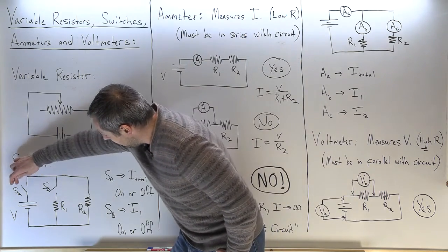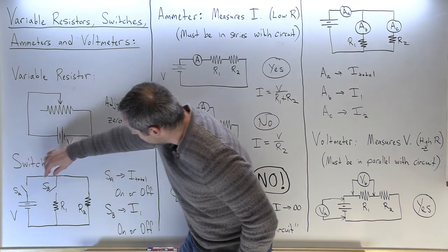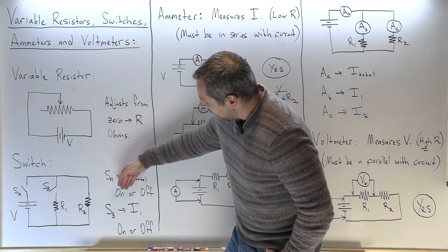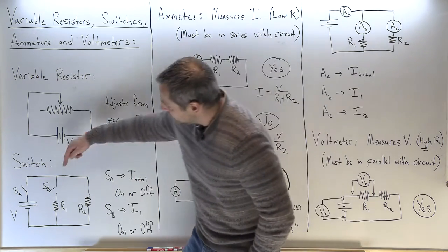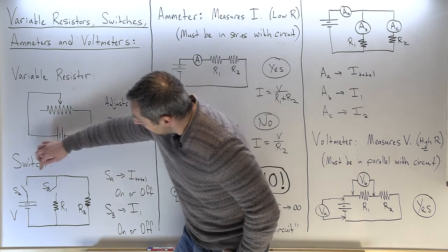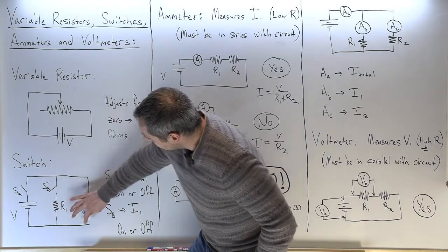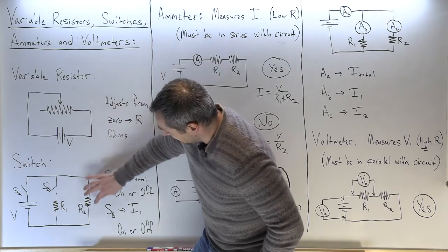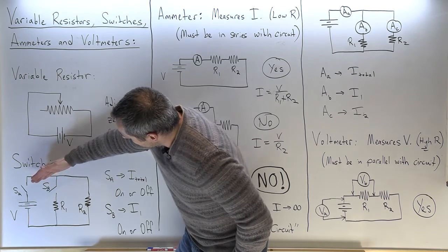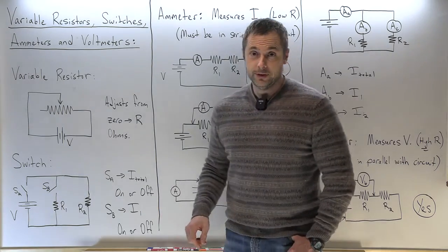So I open it, and then when I switch this down, it makes a contact. Now electricity can flow past switch A, so it controls the I total, making it on or off. Switch B, though, cannot control resistor 2 current, because once this closes, the current can go through resistor 2 even if switch B is open. So switch B will only control I1 on or off, okay?